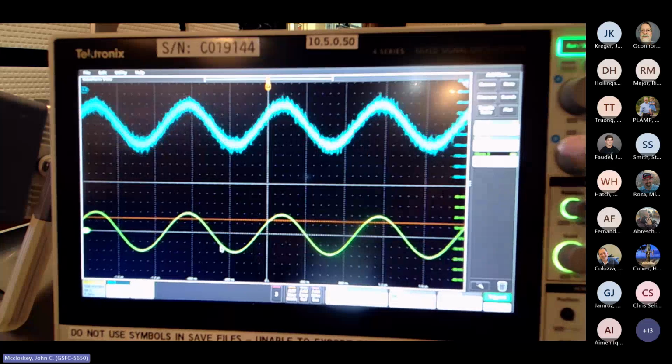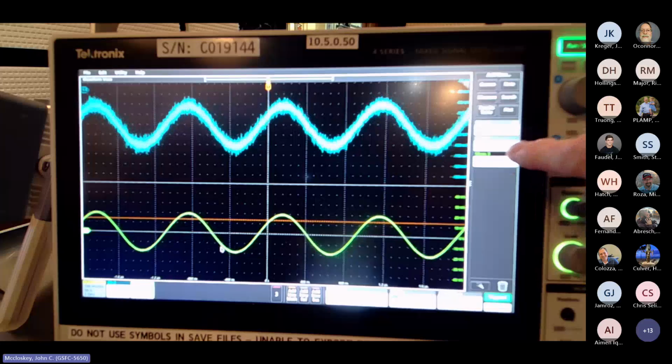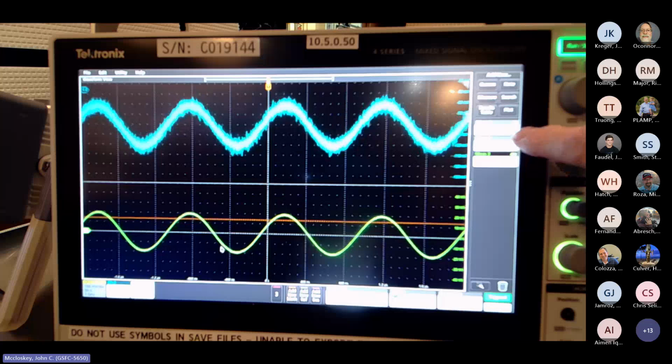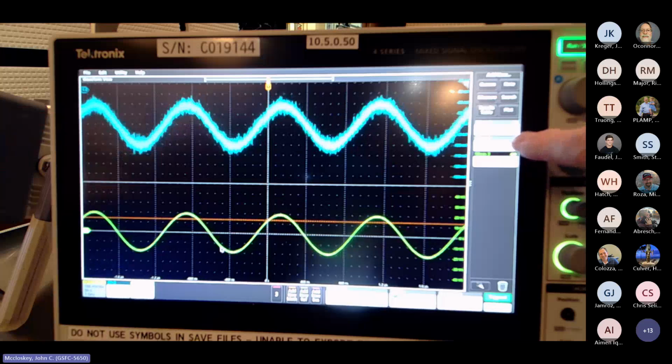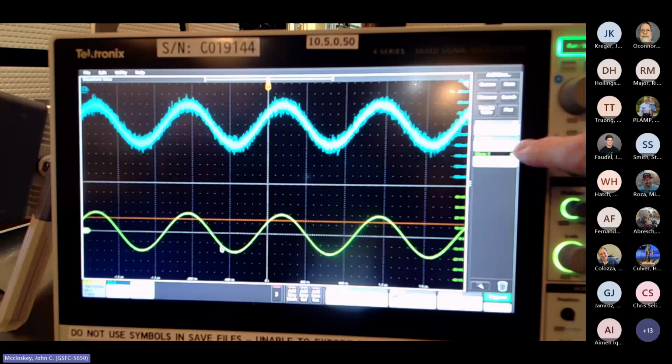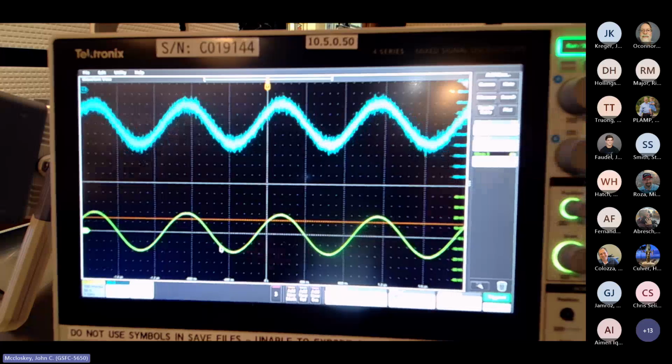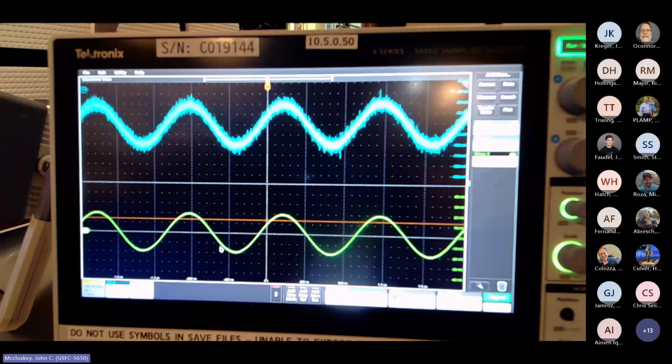Okay, so now again, you can't read the numbers, but measurement 2 is for the blue trace, which is the Hall effect probe we have been looking at. That's 14 milliamps RMS. Measurement 3 is the green trace for the Fisher current probe, and it's 13.7 millivolts RMS, which is 13 milliamps RMS. So they're getting close to the same value, and the noise that's riding on top of the blue trace is probably giving a slightly higher value.